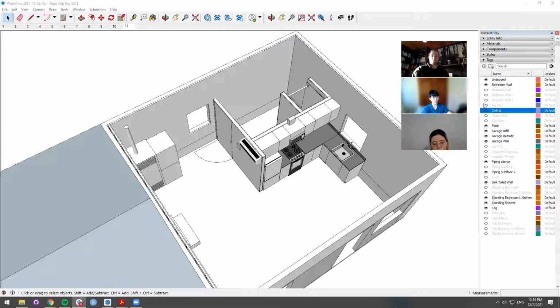All right, Forrest, you wanted to jump back in? Yeah, I just wanted to add some experience on floor leveling compound. It is not as great of a product as it says or intends to be. So I would strongly hesitate to rely on it to quote unquote fix a garage floor. Instead, with regards to ensuring walls are vertical and floors are level, all of your components should have the capability of being shimmed or adjusted or trimmed so that they appear level or flush, because you're never going to get the right angles that you're shooting for, even in new construction.